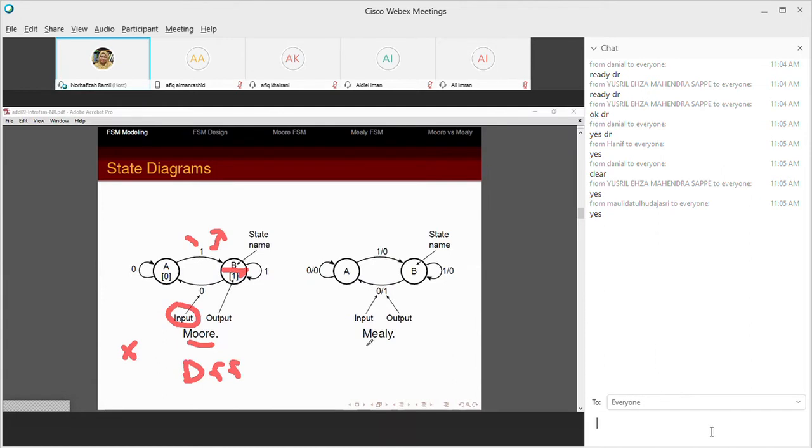Now on the second one, the Mealy machine, on the other hand, your state is clear. Inside the state is just the state name or the state code. So your output lies during the transition. That is why your output not only depends on the state, but also on the input. Here, the output doesn't depend on the input. So usually you have to write X slash F, or whatever you want to say for the output. So this one is X, this is the output.